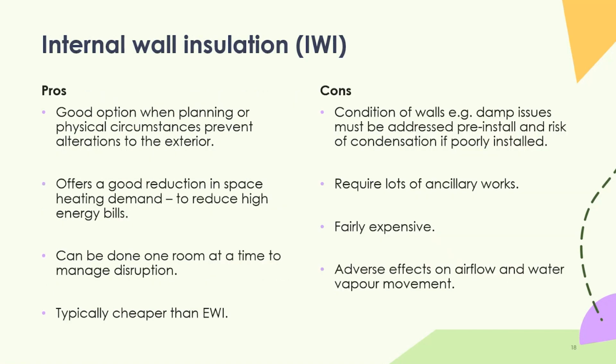Some of the pros and cons for internal wall insulation. Good option when planning or physical circumstances prevent alteration to the exterior, as I mentioned. Usually offers good reduction in space heating demand, helping improve fuel bills and resident comfort.